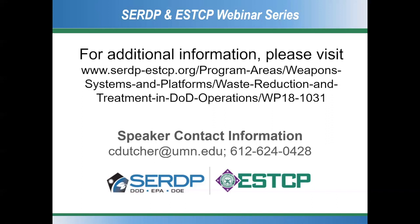And as you move down to droplet sizes that are on the order of the wavelength of the light, it begins to interact with light quite differently. So you really want to be above that when you're thinking about these turbidity measurements and trying to get meaningful information out of that. For all these optical techniques, that's what you're thinking about: are you above that wavelength or not?